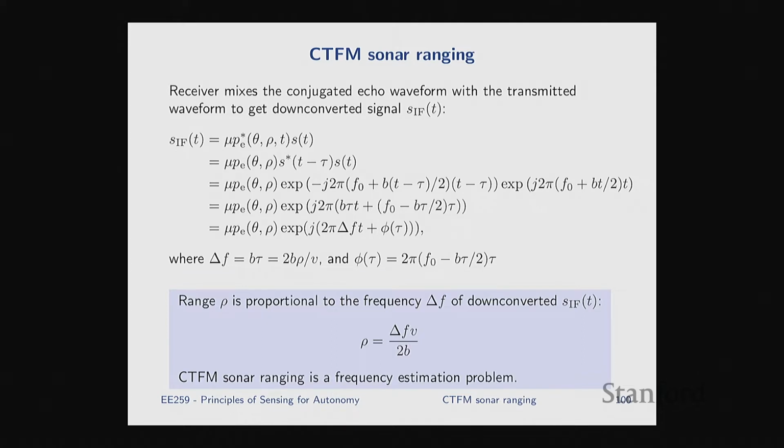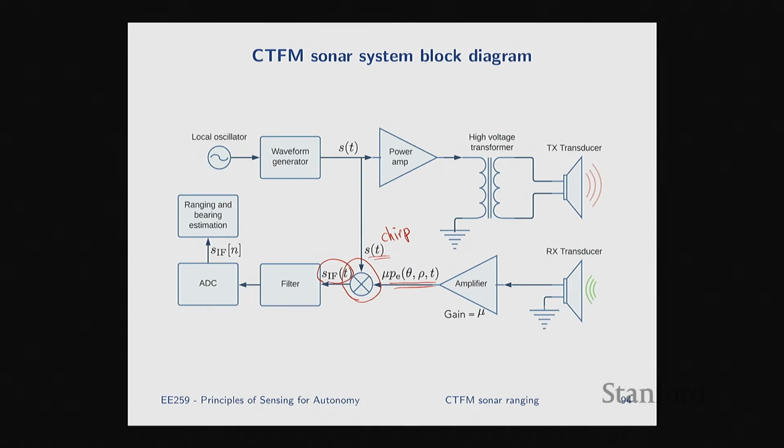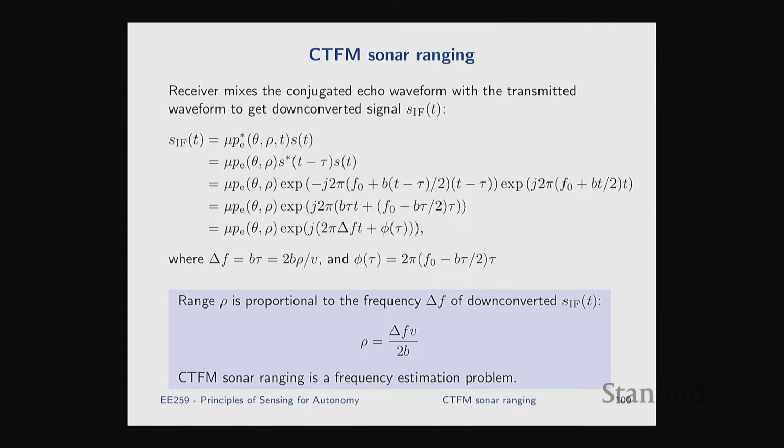So basically at this point, we have a sensor, right? Because that block diagram that we showed, if you build that, the intermediate frequency that we get, if I just go back to the block diagram real quick so we can look at it together. So this intermediate frequency signal, it's going to get filtered and passed through an ADC, but then the discretized version that we have, this signal has a frequency that is proportional to the time of flight. So now to estimate time of flight and ultimately range, all we need to do is to estimate the frequency of the IF signal, right?